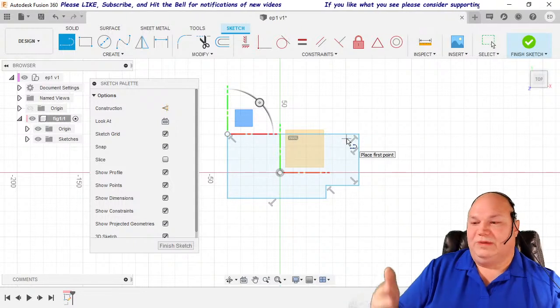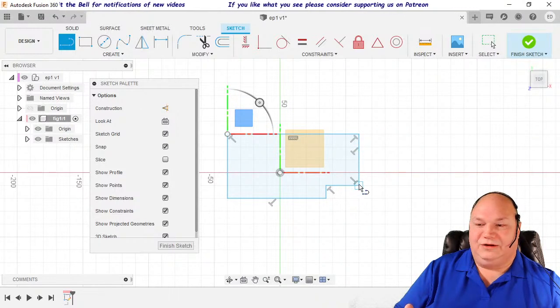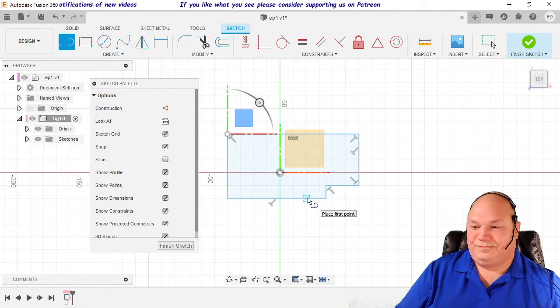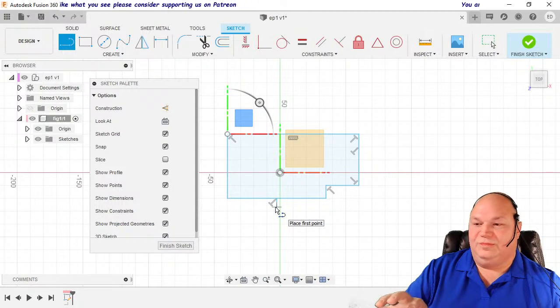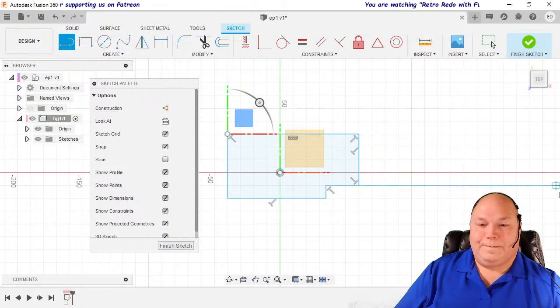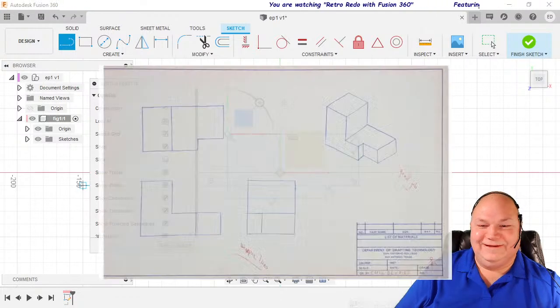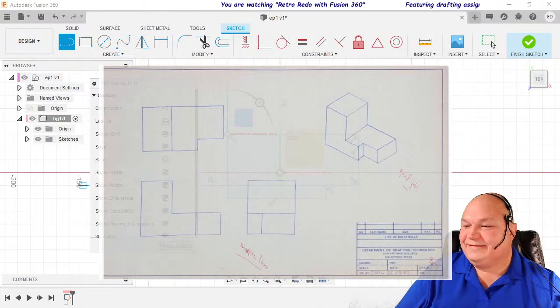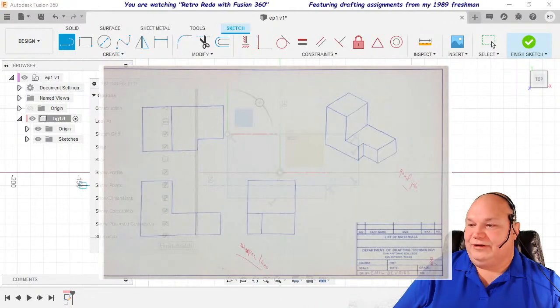We just know basically how they're laid out, and that each one of them is at a 90-degree angle to the other. And those constraints are what's going to keep the shape in shape as we now size it as we need to size it. I keep going the wrong direction with the mouse, but other than that. So now we have our general outline of our shape here.